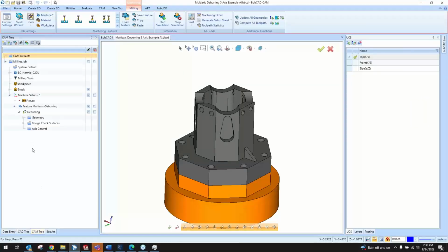And then you had the 4 and 5-axis indexing to be able to rotate the machine to get to a certain index, either on a rotary table or on a trunnion, or the head's able to rotate around to index to a certain location and do your 2 or 3-axis milling from there.